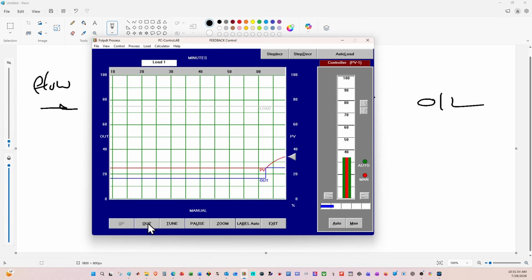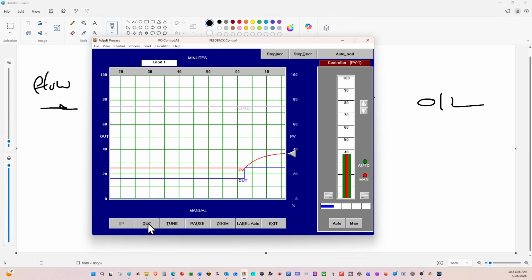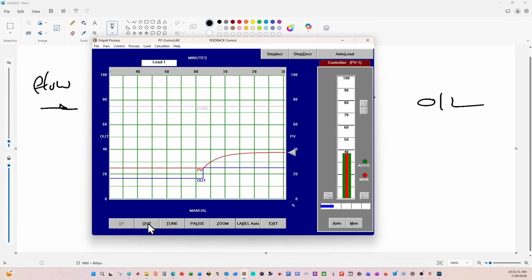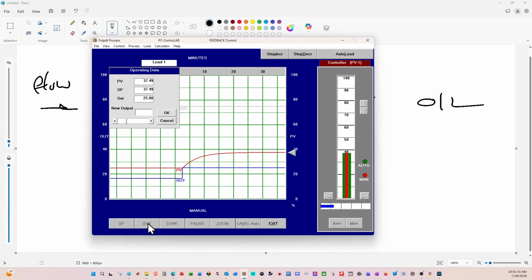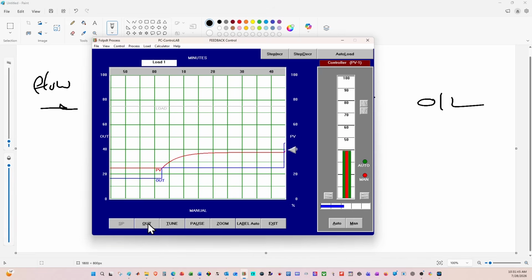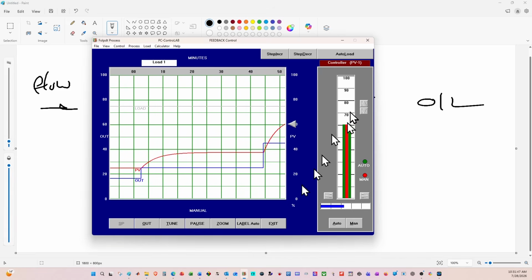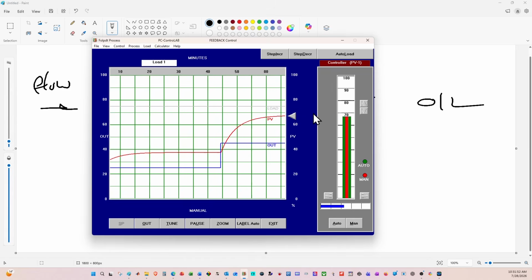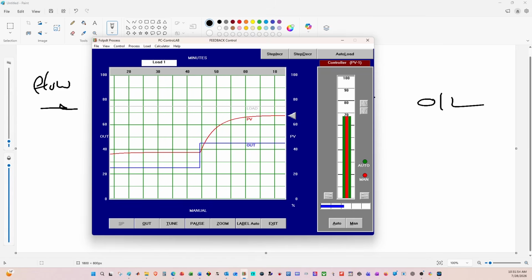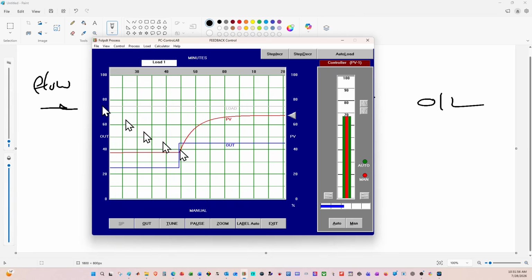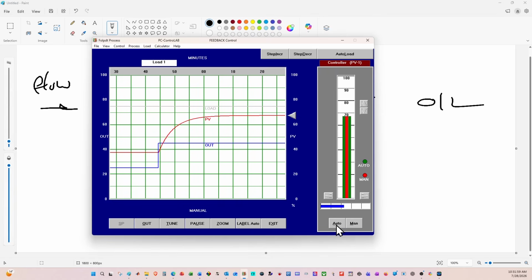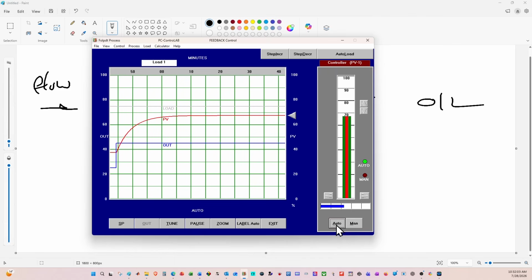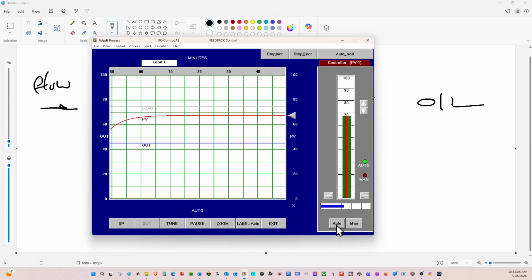Look at how the process variable follows the set point, or how the set point follows the process variable. There's tracking that we have got. Let's change that output and maybe take it up to 45%. And once again, you can see the automatic tracking that is happening on the right-hand side, which is there so that the second I put that process back into automatic, we're already at the set point and we're not going to have any bump in our transfer.